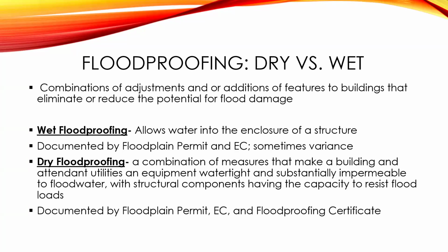Again, wet floodproofing allows water into that enclosure or structure. Dry floodproofing uses these different elements to make a building and attendant utilities and equipment watertight and impermeable to floodwater. So those components have to have the capacity to resist the flood loads.